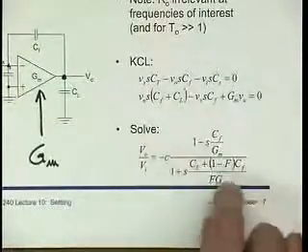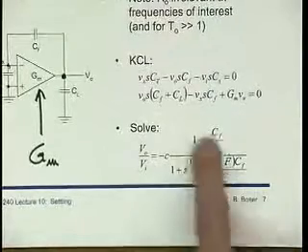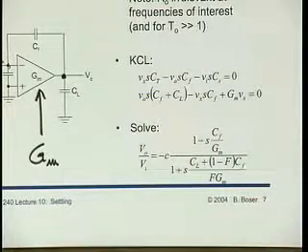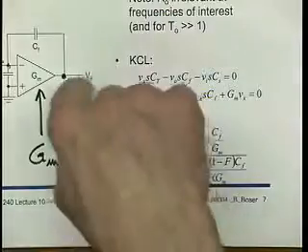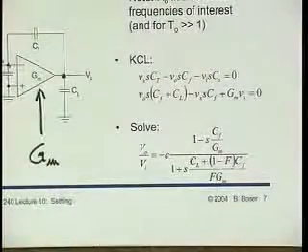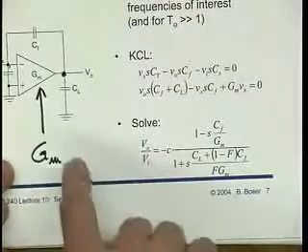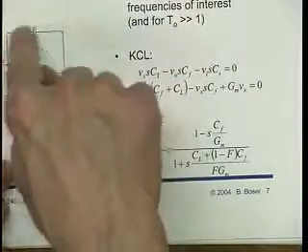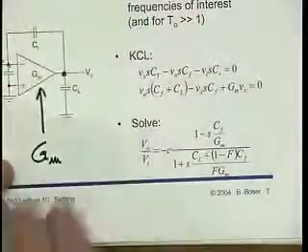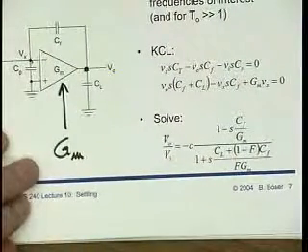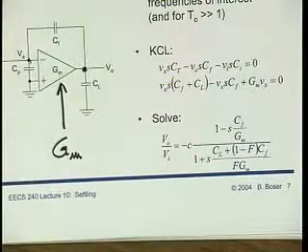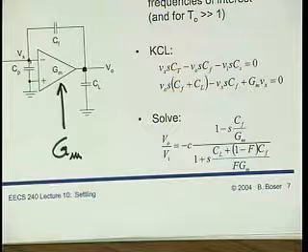Notice again, the phase margin of this is totally immaterial for stability. If I wanted to put another feedback loop around all of this, then I would be concerned with the phase margin of this. But for stability, I would have to check into this feedback loop alone. We've done that in the earlier part of this lecture, so now we've assured that the circuit's stable.